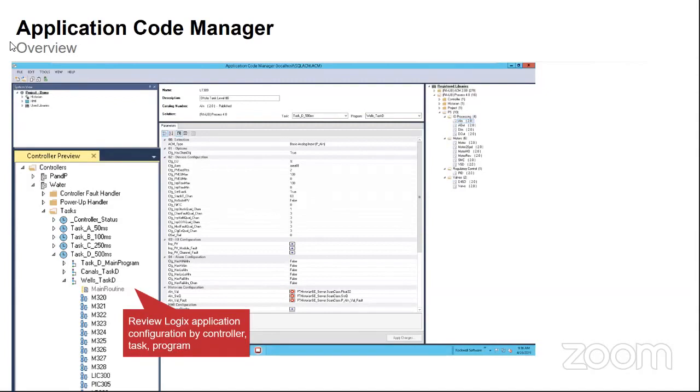For the most part, this is what we've all been doing in coding world with XML in the past. This is putting everything together for you. So thankfully now there's a program off the shelf that you can use instead of us building something out. So the next step on this thing is it will build out your logic. So again, you're looking at it from your routines, your tasks, everything that's there. You're setting the default so it knows where you want to stick it. So if you're using an analog input, more than likely you defined it to be either the 250 millisecond or the 500 millisecond rate. So it's automatically going to move that in.